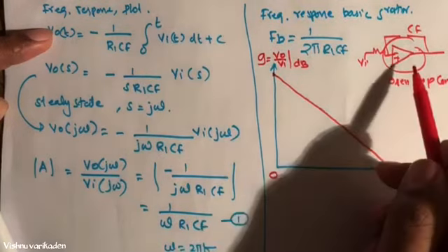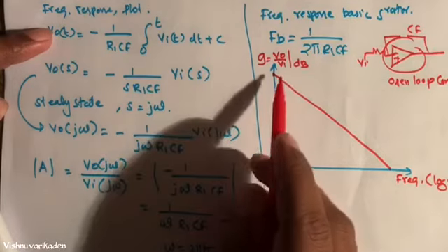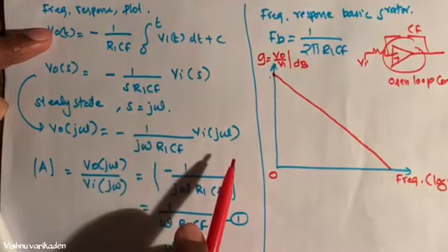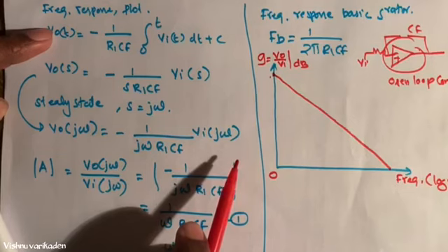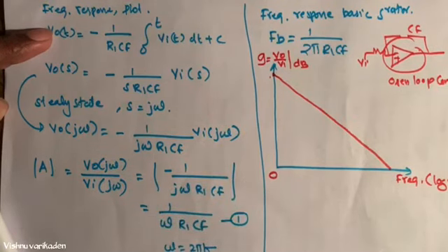So there is no negative feedback. In the practical case, the gain does not go to infinity; rather the output of the amplifier saturates at a voltage, close to the op-amp's positive or negative power supply depending on the polarity of the input signal. This is the saturation voltage, and then we get the response here.